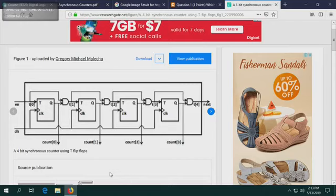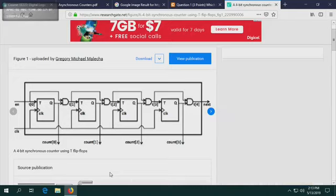So how do we suddenly intervene in the middle and clear everything, make it all 0? The way you do it is by using the preset or the clear. If you want to make a particular flip-flop or all of them 1, use the preset. What do you provide to the preset? You're going to provide an active 0, active low.